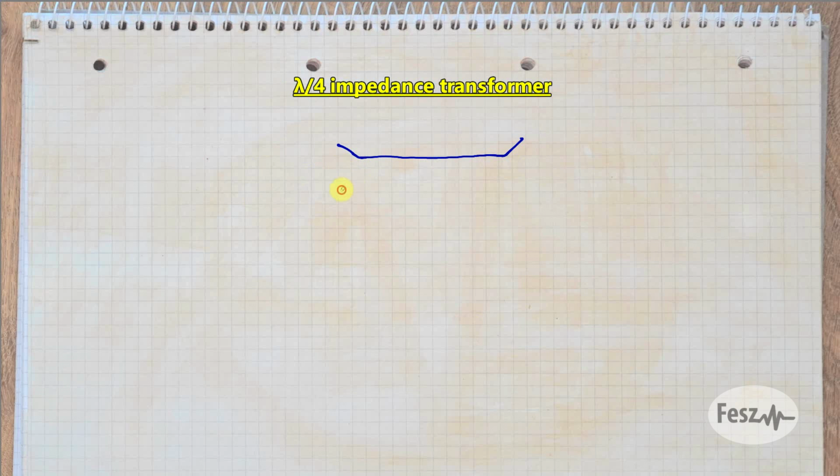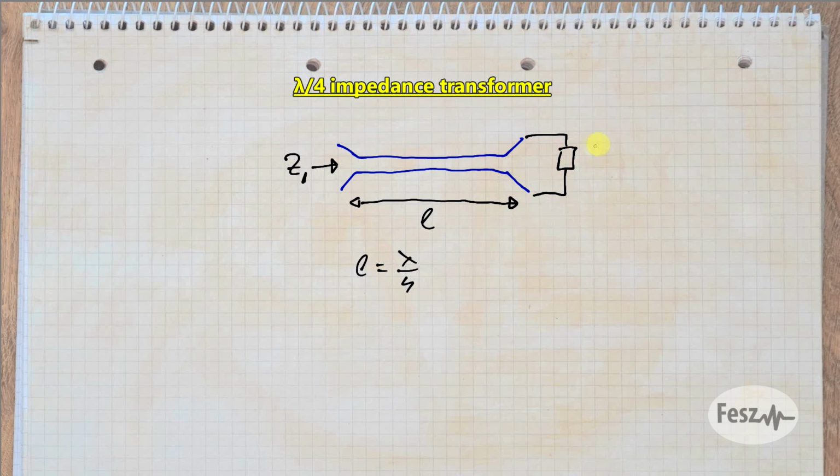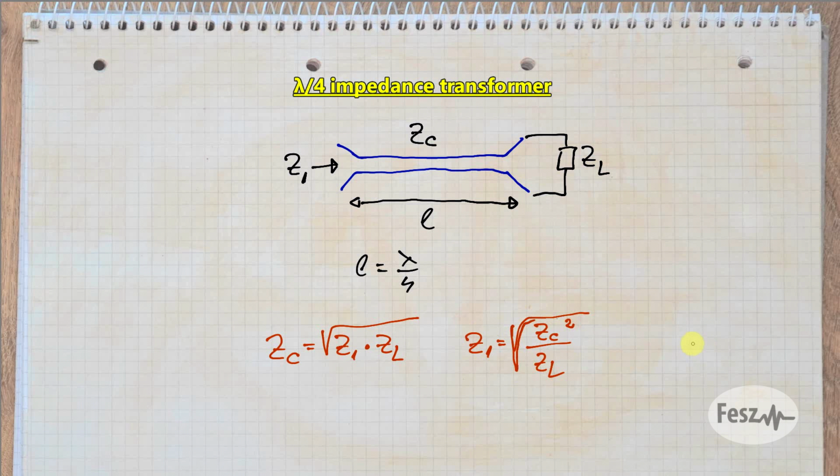To better understand the stepped impedance transformer, we need to start by remembering the quarter wavelength transformer. So when analyzing the structure, an impedance transformer in which two resistive impedances are connected with a piece of transmission line that is a quarter wavelength long and has an impedance equal to the square root of the product of the end impedances, or if it makes for a better understanding, the impedance as seen from one end is the square of the line impedance divided by the end impedance.